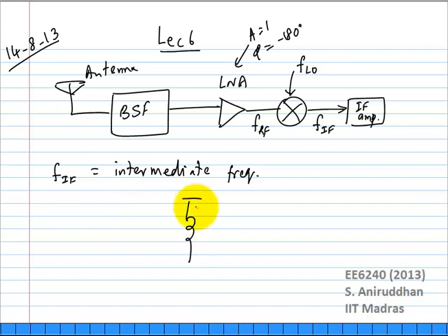So let's take a very simple common source tuned amplifier. So let us say this is V in, this is V out. So I may have some parasitic gate drain capacitance on this transistor, which is giving you a parasitic feedback path which could degrade your phase margin. Correct. If you analyze this as a loop, the phase margin will depend on the value of this capacitance, right? Okay, so when will this capacitance be large? When the devices are large.